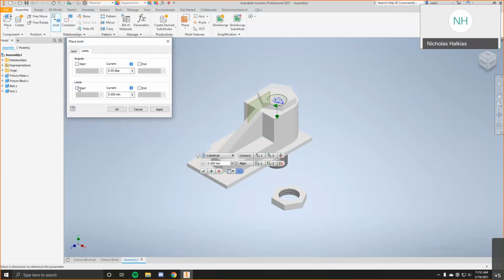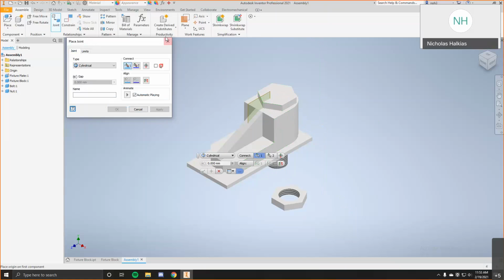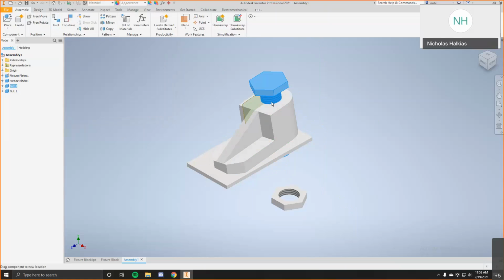But if we want to make a linear constraint, we're going to have to make a start and an end point. The positive and negative direction isn't always evident, so you can just put in a number for the current. So the positive direction is down in this case. That means we can make our start point at 0, and then we can make our end like negative 70 millimeters. So now, you'll see if we apply this, when we get out of the joint menu, we can...